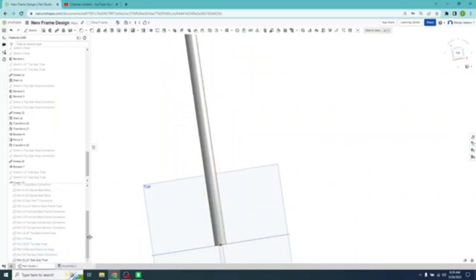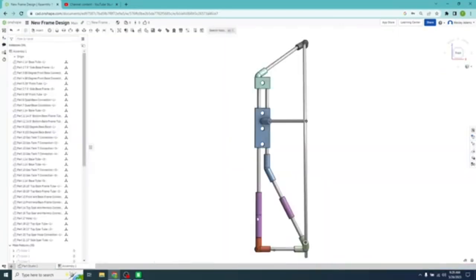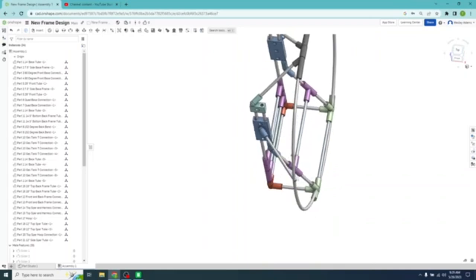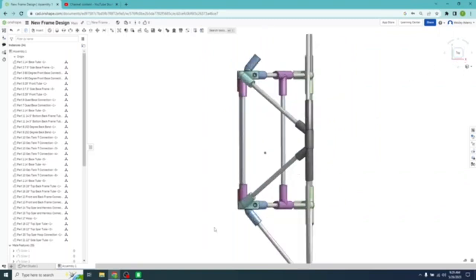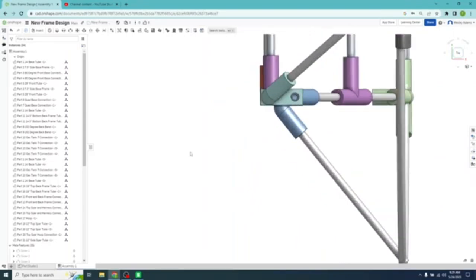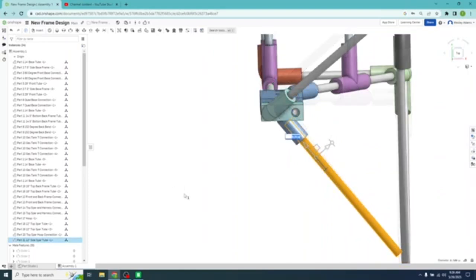Now, since we're using those slider mates, we may have to redo the slider mate. It may adjust that when we import back in. Let's go back and see. And even though it's in the same location here, you'll notice, I believe, let me scroll in, if this is the same as what happened for the other ones. Scroll in. Now you notice it was 1.5 inches in here, so now we're going to have to move that in. Let's keep it there.